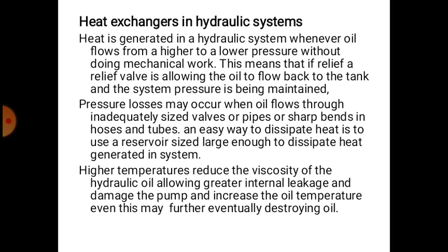Temperature of the working fluid also influences the performance and hence efficiency of the hydraulic system. Excessive heat hastens the oxidation of the fluid and reduces its viscosity. This leads to deterioration of seals and packagings and accelerates the wear between closely mating parts such as valves, pumps and actuators. Similarly, low temperature of the fluid increases the viscosity, resulting in loss of power and poor response of the fluid. Significant sources of heat include pumps, pressure relief valves and flow control valves.